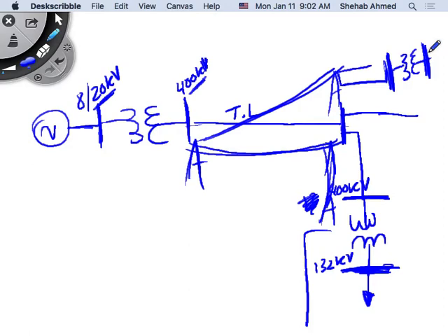The transformer at city center, in this building that's taking half the building, I believe that is a 66 kilovolt to 11 kilovolt transformer, right? So what does that mean? It means that here, if I'm saying this is 400 kilovolts, I should have added another area here where I took this 400 kilovolts and converted it to what?